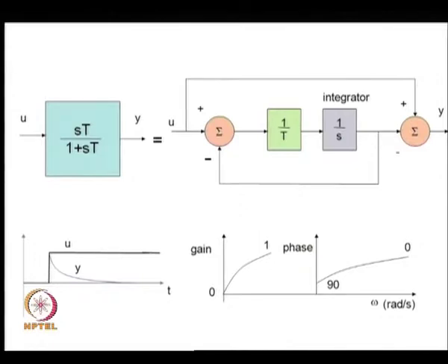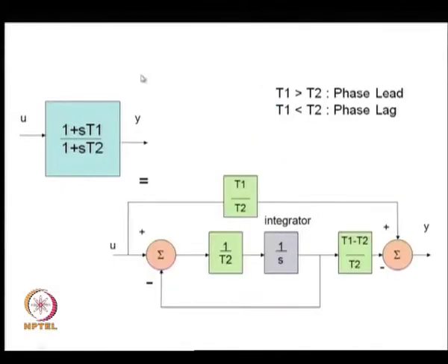So, it does not interfere with the regulation function in steady state, okay, if used in conjunction with an automatic voltage regulator. On the other hand, a phase lead or a phase lag block can give appropriate phase shifts and even magnitude shifts, or an appropriate gain, which is frequency dependent. Okay. So, this is also a usual component in any power system stabilizer.